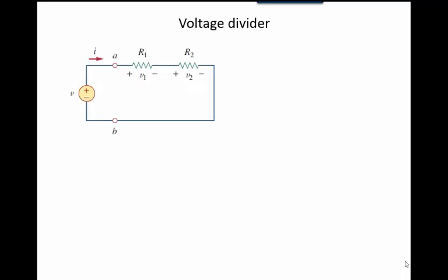So more examples. The first one's kind of a simpler example, but it's an important concept because a circuit like this is called a voltage divider. Voltage dividers are used in all kinds of much bigger circuits. A much bigger circuit might be powered with 12 volts, but somewhere inside the circuit you need 5 volts. So you have to divide the voltage down, and it's done with a circuit like the one that you see on top here. So voltage dividers, how they work.